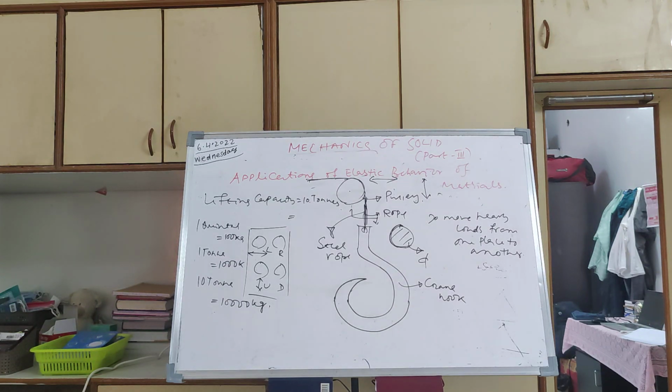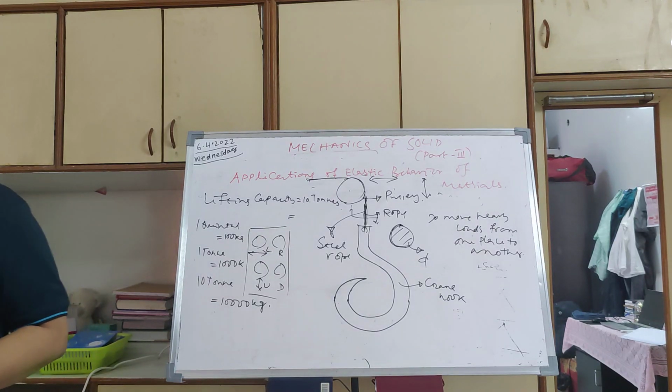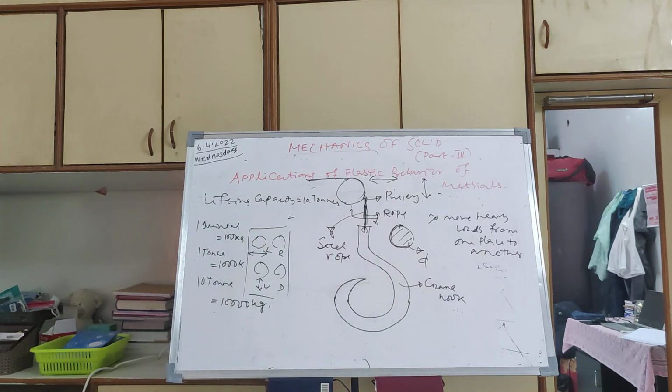The extension should not exceed the elastic limit, meaning there should not be any permanent deformation. We have done the proportional limit, then elastic limit, ultimate, then the tensile.